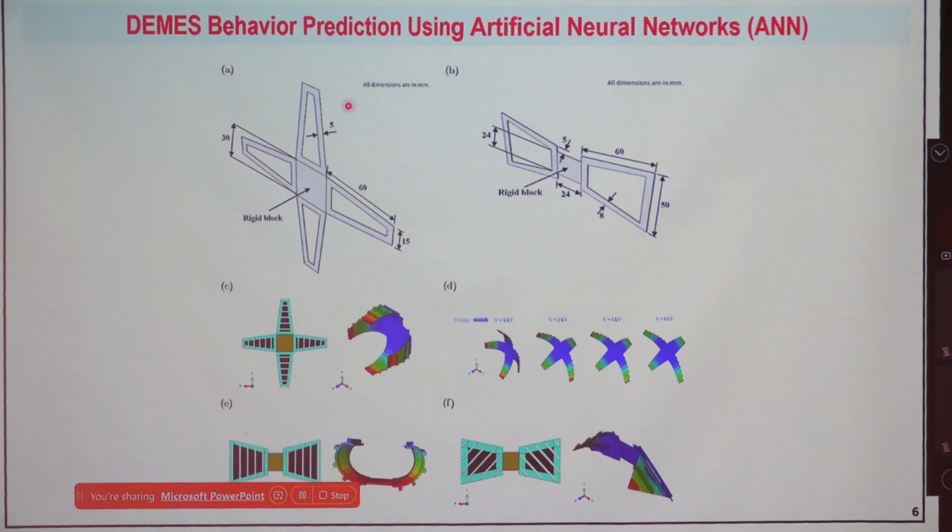If you directly put the frame over that and obtain the equilibrium configuration, after 1 or 2 days you will see the angle you got has changed. So you are not getting the accurate result. So experimentally you keep it for 24 hours, then you fabricate everything, you put it, you cut it, you apply the voltage. So for one equilibrium configuration it will take 25 to 30 hours. And one simulation will take 5 to 6 hours.